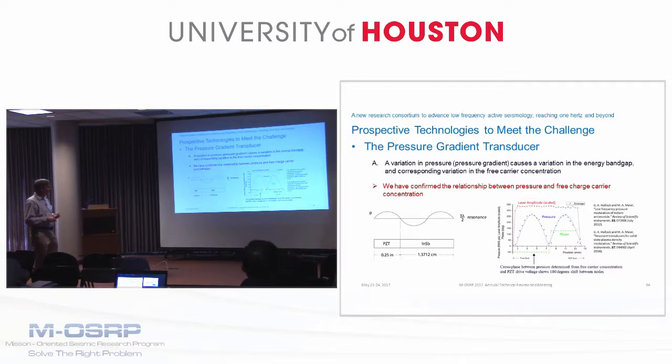And you can see a double lobe amplitude here, just as you would expect in a single wavelength standing wave pattern. And then in addition, what's shown here is the relative phase, and they are 180 degrees out of phase. So we're getting the right dynamics in the measurement, and we're getting the right amplitudes, which agree with the amplitudes mechanically that you expect out of this system.